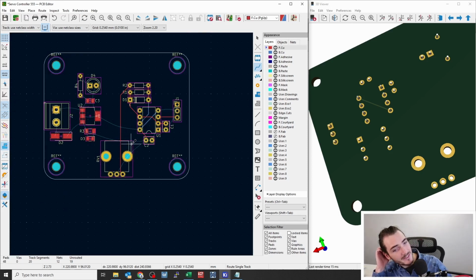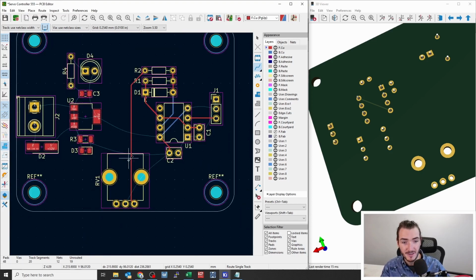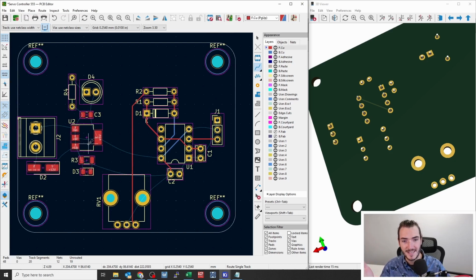And this is where you start running into design constraints and design problems, because we've got this trace that's spanning practically the whole board. And again, it's going to be fine. It's a simple circuit. But when you do something like this, be aware that you're creating a constraint. You can no longer pass traces horizontally unless you're on another layer. As it turns out, we only need to get power and ground across these two parts of the circuit board, so this will be fine.